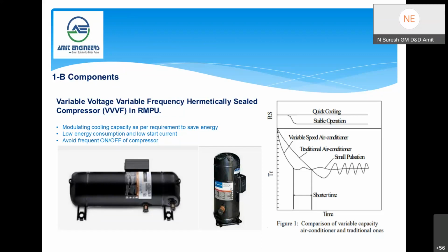So when reducing the frequency, the voltage will also be reduced, proportionally. Voltage and frequency both have to reduce proportionally. We cannot reduce only voltage or only frequency. In that way, the power consumption or power requirement will be reduced.